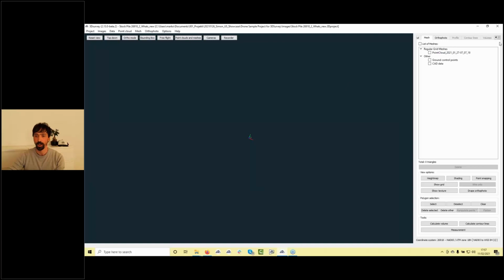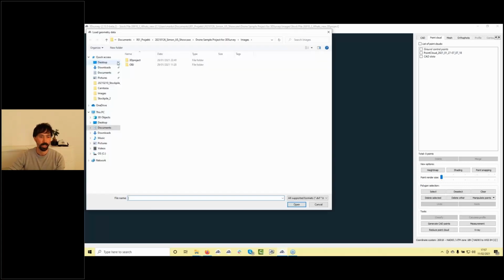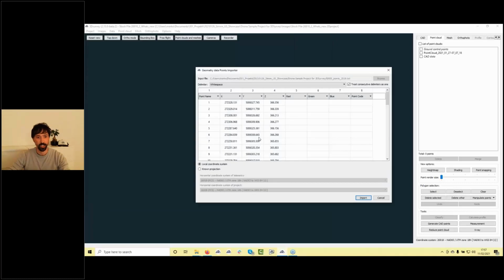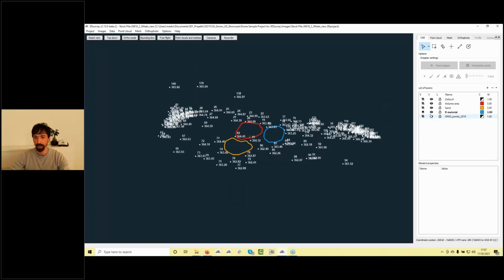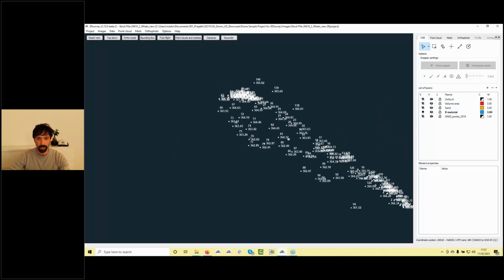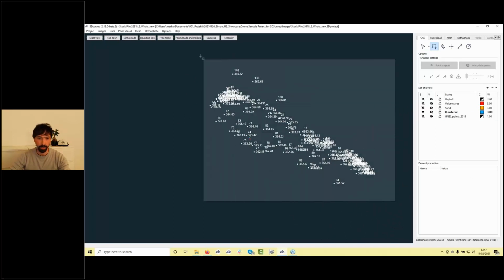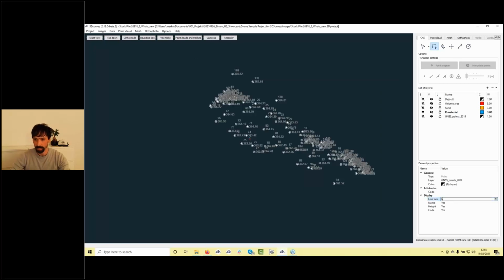So I will turn off my regular grid mesh, I will go to my point cloud, here is the existing one, and now I will load my points which were measured actually 2 years before with the GNSS measurements. We see point name, X, Y, Z, local coordinate system, import them here, and I have them here. Let's turn all other layers off. Cool. These are my 3D points, maybe smaller. The text size really quickly, the 6.